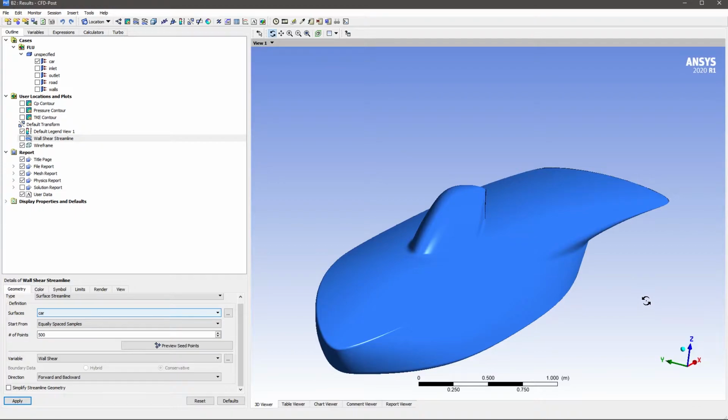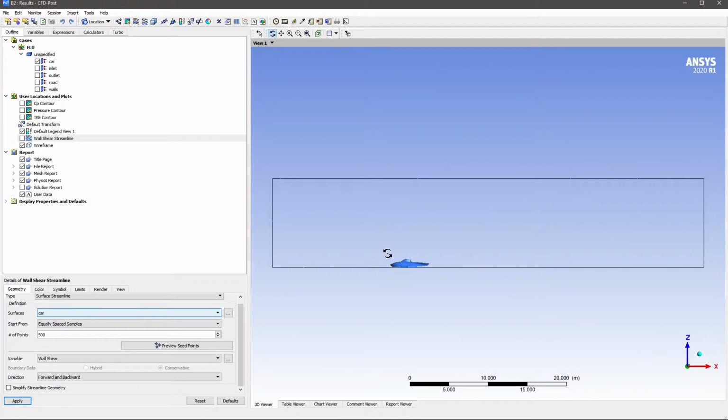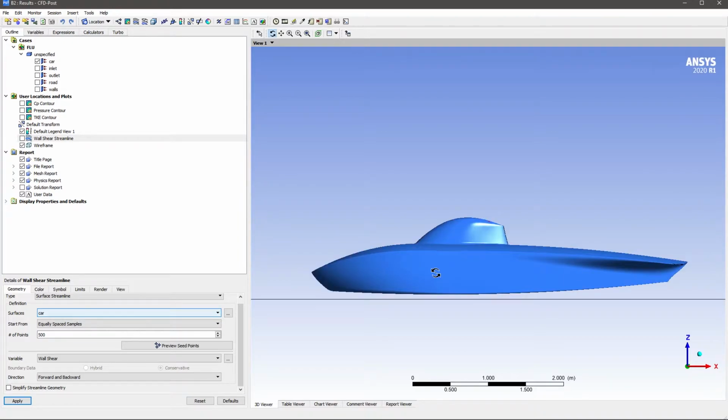And this is where knowing the coordinate systems becomes really important, just so you can quickly pan around and select preset locations. I'm going to select the -y arrow in CFD-Post and the coordinate arrows in the bottom, and that will bring me to the left side of the car. Click and hold the right mouse button to select an area that you want to view of the car.